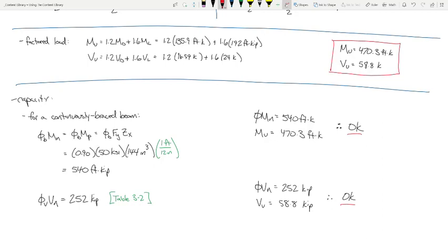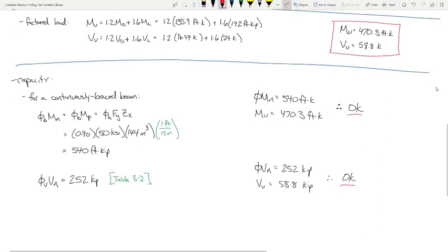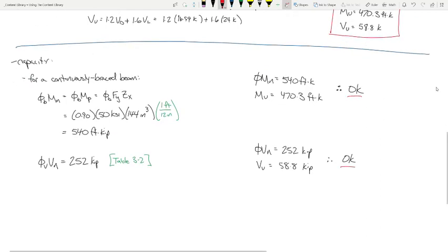And again, the performance ratios for shear are just really low. Steel beams in buildings just have a lot of shear capacity. Except, I mean, there are some instances like with transfer girders and whatnot, but for most standard everyday beam design, shear ends up not being a problem.